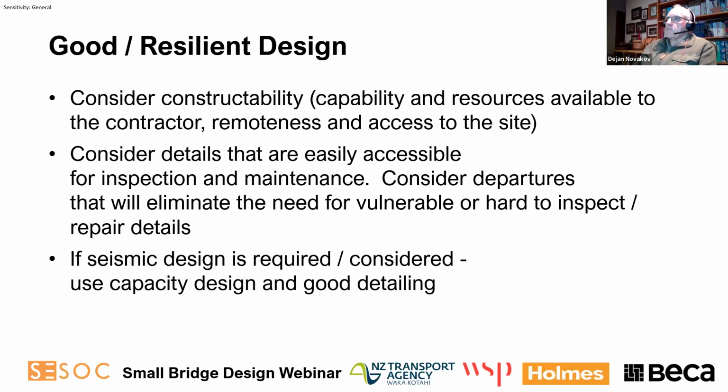In addition to what Geoff nicely covered about what you consider in your design, I'm just going to repeat it again. Consider constructability, so capability and resources available to the contractor, remoteness and access to the site. Consider details that are easily accessible for inspection and maintenance.